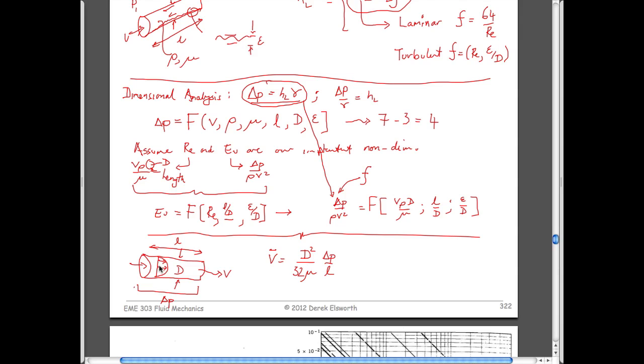Right at the wall, the velocity would be zero because the fluid, if you like, is attached to the wall, just like in our calculations for viscosity. And so what we'd be using in this particular case is we'd be presuming that Newton's law of viscosity is the shear stress equal to the viscosity times the change in velocity with radius. This is the radial direction.